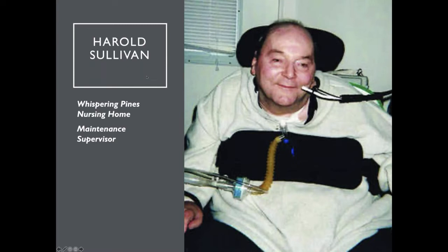Harold Sullivan, who was a director of maintenance at Whispering Pines Nursing Home, had a boiler that would not start. And Harold kept pushing the reset button on the boiler. Well, eventually the boiler filled with gas, and after the fourth time of resetting it, he pushed a button, and it hurled poor Harold across the boiler room floor about 30 feet into a wall, and Harold spent the next 10 years of his life in his wheelchair.